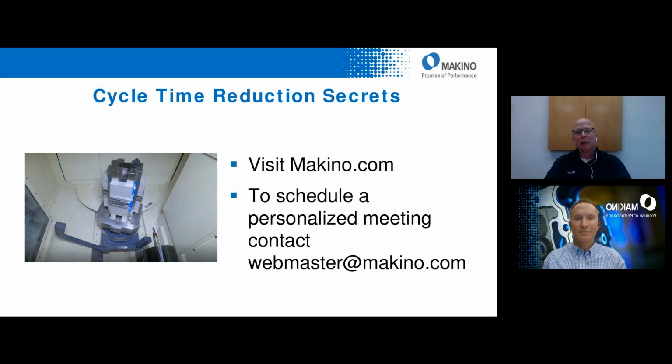So again, you just methodically take your time and go through and prove it out, both theoretically in the CAD CAM system and your simulator, things such as Vericut, a simulator you can use, NC simulation, and then obviously on the machine, and you'll reap the benefits of that. I mean, you saw a second and a half, 2 seconds just on that simple demonstration of a savings, and you do that across multi rotation programs and positioning, and you're going to realize quite a bit of savings.